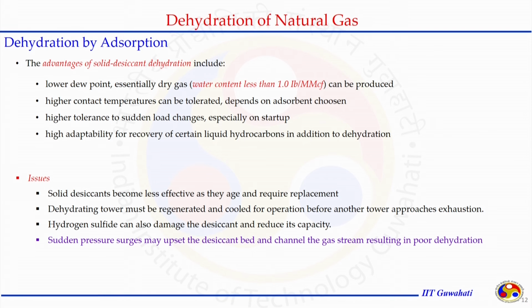Certain issues are there, as with any other process. The issues with the adsorption dehydration process are that solid desiccants become less effective as they age, meaning over time when they are getting used, because of the contamination present in the natural gas, because water is getting accumulated, and because they go through the regeneration process at a higher temperature, the efficiency of those solid desiccants becomes less, and after a certain time, the usual life being 1 to 4 years, replacement is required.